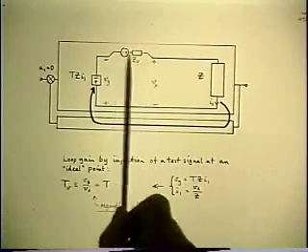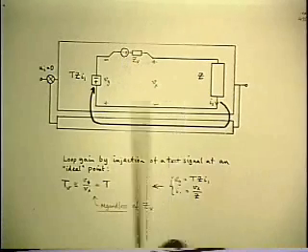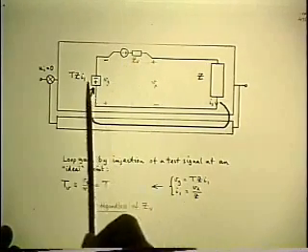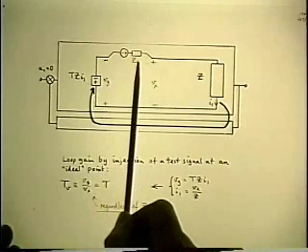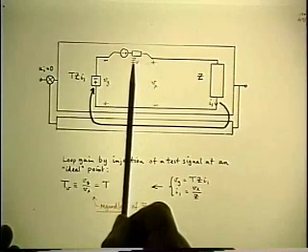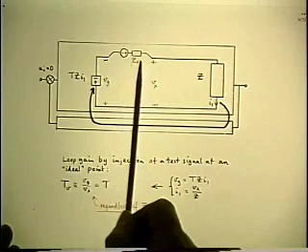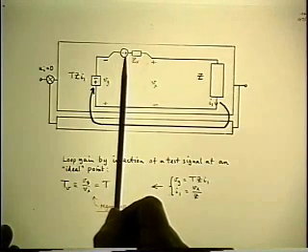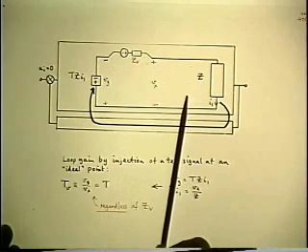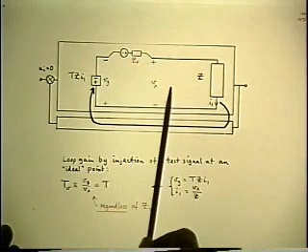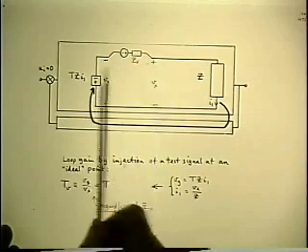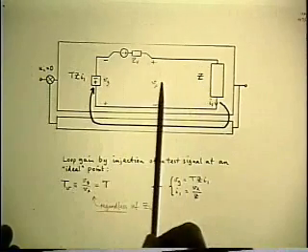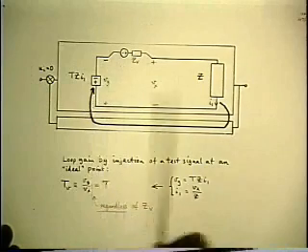And I mentioned, sort of as an aside along the way, if we're talking about non-ideal injection points, we better also talk about non-ideal injecting sources. So I said, I'm putting this impedance in series with the voltage source, and I'm doing the same thing when I put current sources there. I'm putting an impedance in parallel with it. So I've incorporated non-ideal injecting sources all the way along.